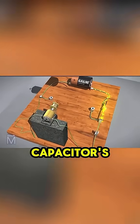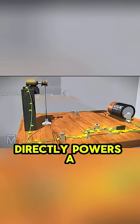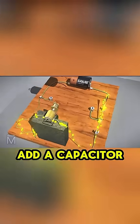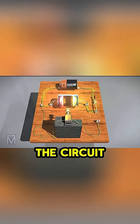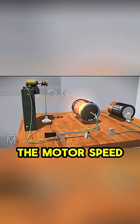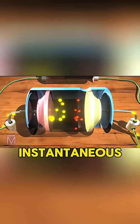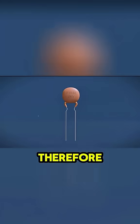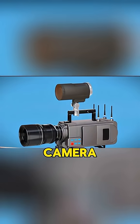Furthermore, a capacitor's discharge speed is much faster than a battery's. In this setup, a battery directly powers a motor and its rotation speed is slow. Now if we add a capacitor, first we use the battery to charge it, then we switch the circuit to let the capacitor power the motor directly. You can clearly see the motor speed has increased a lot. This is because the capacitor provides a much larger instantaneous current than the battery, giving the motor a greater power output. Therefore, capacitors can power devices that need fast charging, like the flash in a camera.